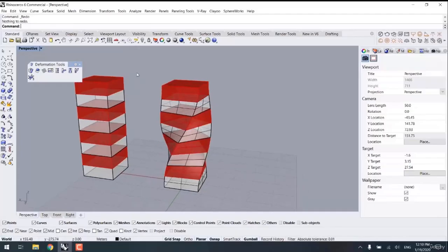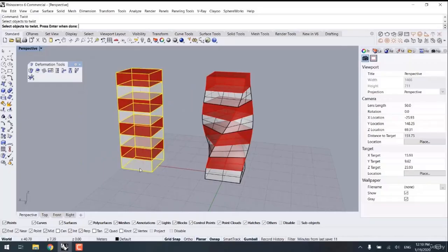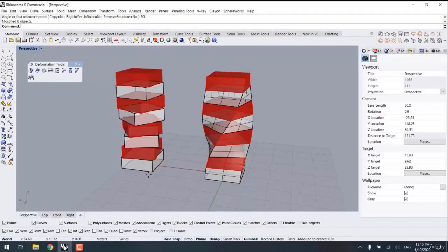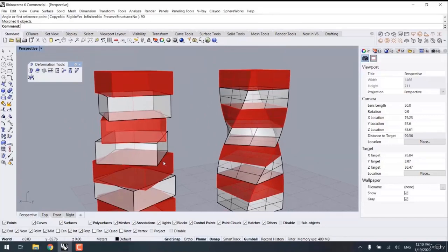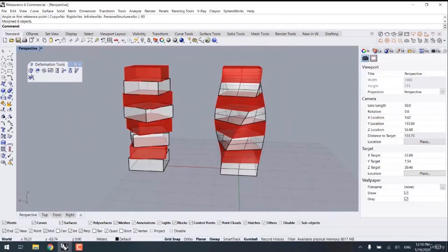And in another case that may happen with twist, for instance, the objects, the axis, and then I set rigid to yes. Following that, the rigid option specifies that individual objects will not be deformed as they are transformed. So if you specify 90 degrees, then individual objects will not change, only their positions will change. And as far as you're concerned, using the rigid option or not is based on your needs.